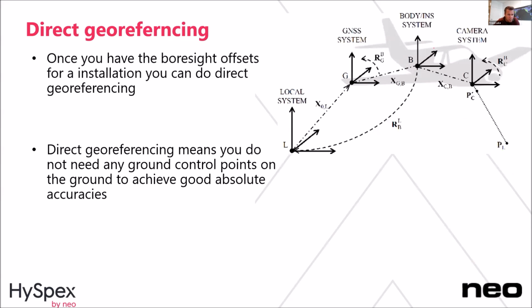for the practical session. So as I said, we are finding the offsets here between the coordinate systems. Basically, at the end, you have an Earth coordinate system that everything is resampled to. And direct georeferencing means that you can do this without any need for GCPs on the ground, which is what anybody wants at the end: not to go out and measure, or have to have an orthophoto to do the auto rectification.